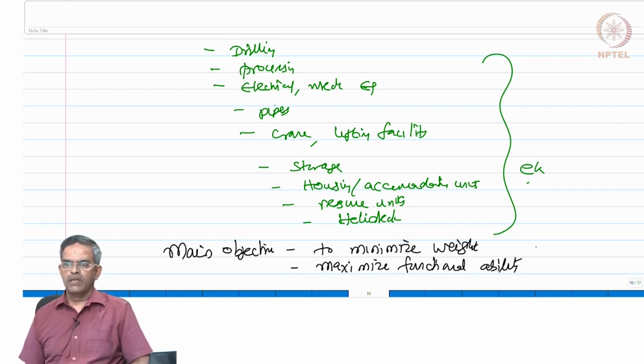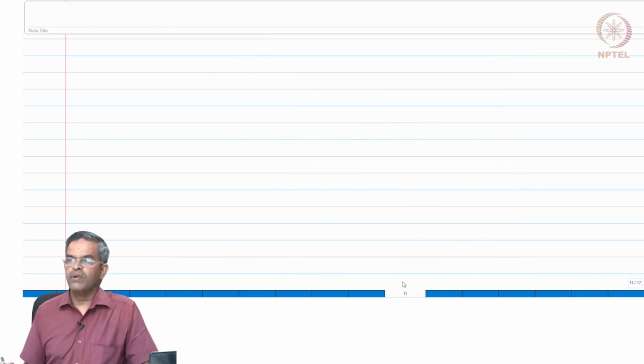So, even the geometric form, arrangement of members, their sizing, placement of heavy equipments, both vertical and horizontal zoning, spacing of critical operations such as lifting, loading, unloading, drilling plays a very important role in balancing the load acting on the structure. Okay? That is very important.